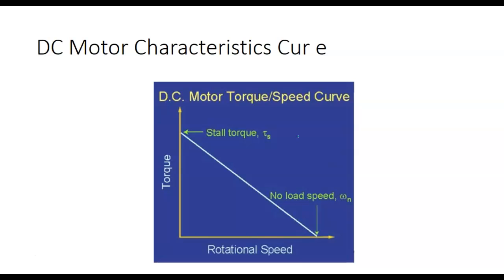So reversing the motor. What's the normal way to reverse a DC motor? Switch the connection on the armature, right? What's the normal way of reversing a single-phase motor? Switch the connection on the start winding. Good. What's the industry standard way of switching a 3-phase motor? Yeah, 1 and 3.